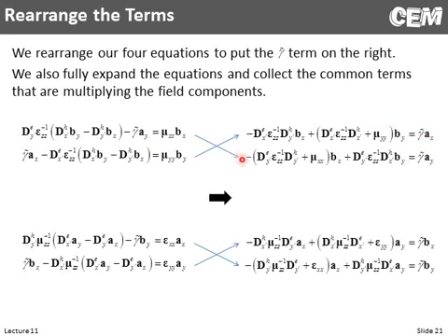So we just did a little bit of algebra on this. We're bringing the gammas over to the right-hand side for both sets of equations. Those are our normalized propagation constants. And everything else on the left, we've collected coefficients on bx and by. And down here we collected coefficients on ax and ay. But it's those remaining four equations now with az and bz eliminated.